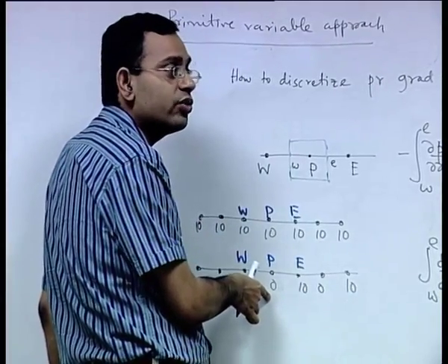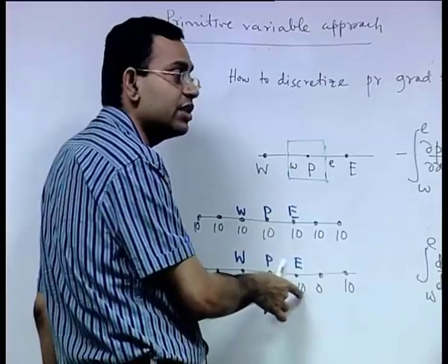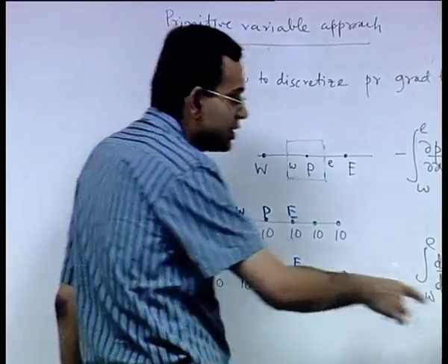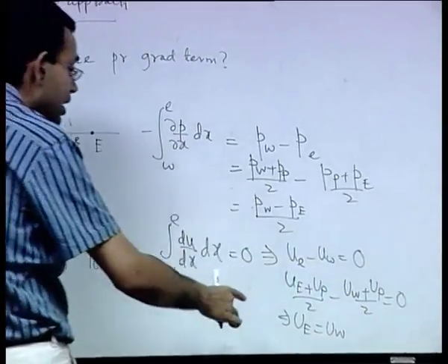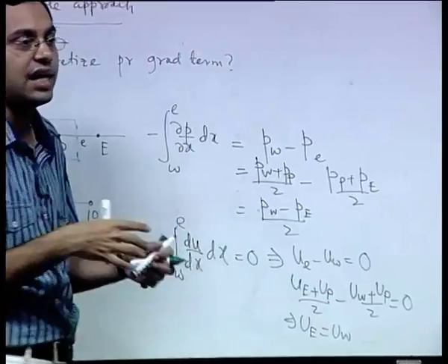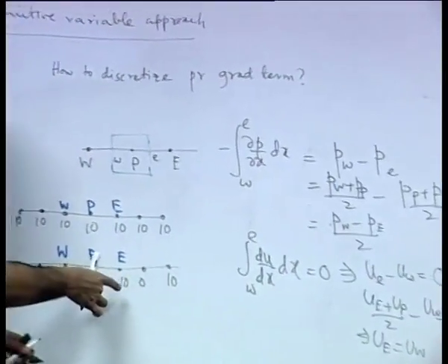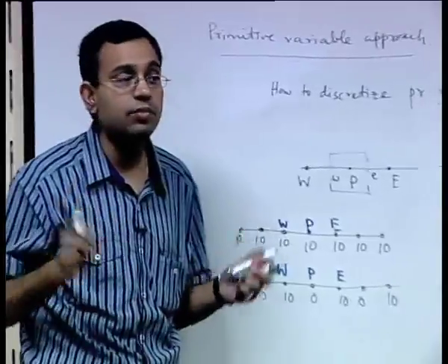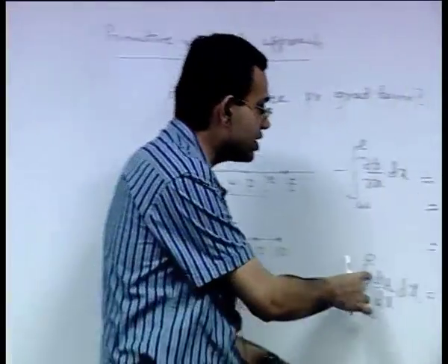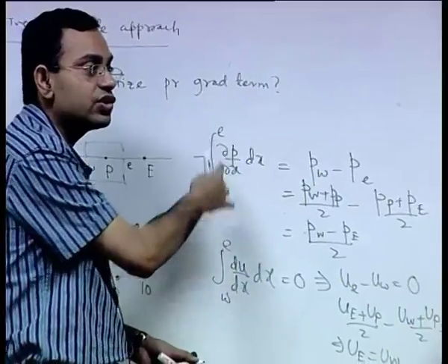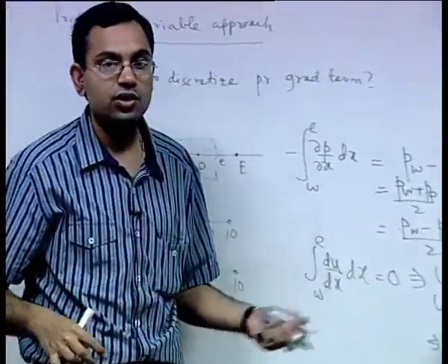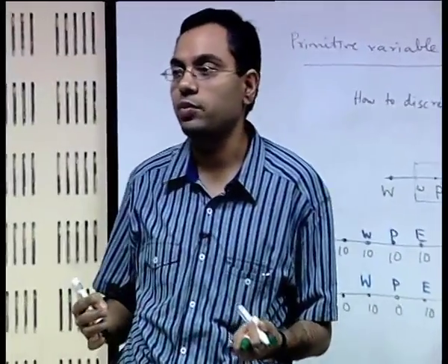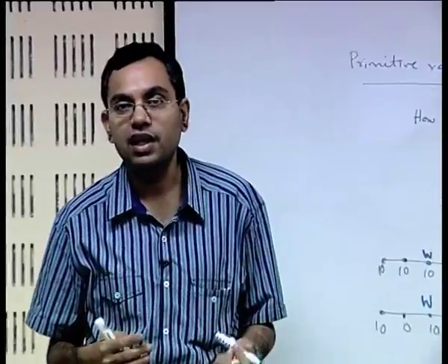Here this is not du dx equal to 0 because u is a function of x, still it is interpreted as u e equal to u w and it gives a false idea as if the one dimensional continuity is satisfied. So, there is something wrong with treating the first order derivative terms in the source term of these equations or even in the continuity equations. How we get rid of this problem, we will take up in the next lecture. Thank you.